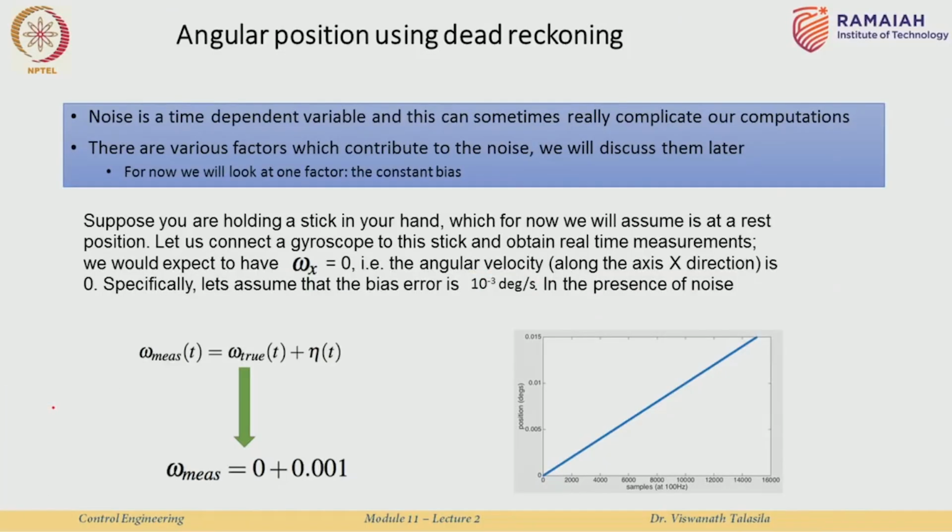To understand that, we need an important thing, which is the sampling rate. This is a gyroscope, a typical MEMS gyroscope. You can sample it anywhere from 50 hertz all the way, I imagine, to around 300 hertz or something. You can even do it higher, but the accuracies are not so good.